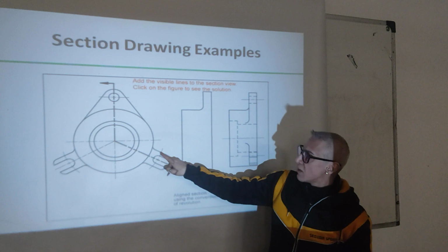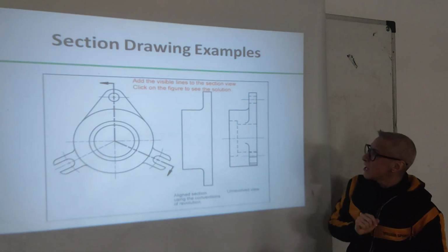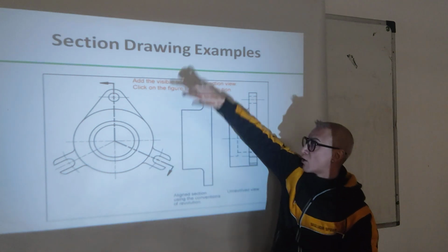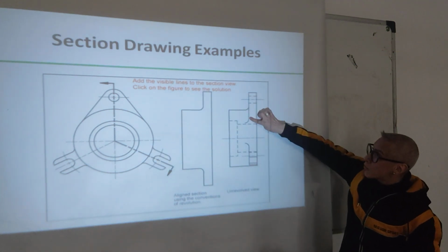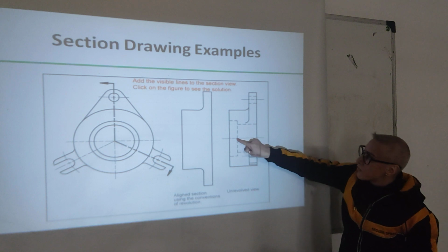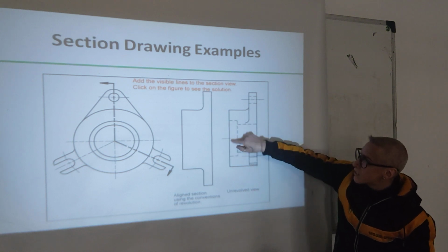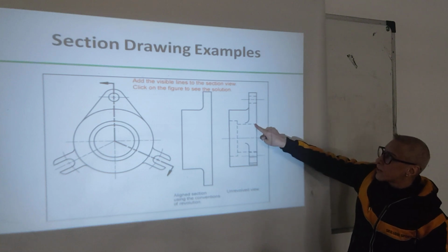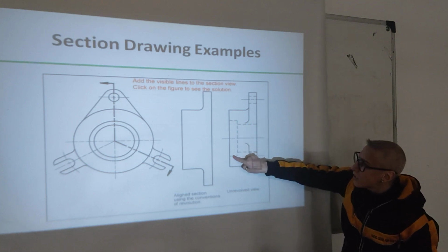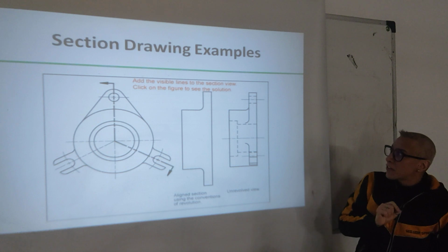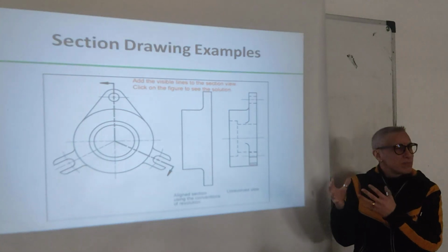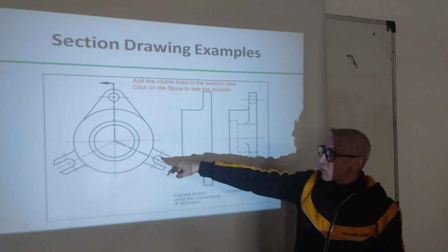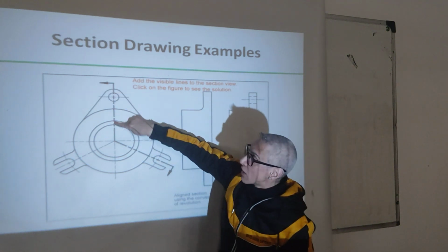We have these lines, which are seen from the outside, because these objects come out of the actual object, so these are object lines. Then inside we have a circle, and this is the midline going through the circle, and then we have all these hidden lines which show the other details, so it becomes a little bit not clear. So the section view, look at this section, how it's done, okay?